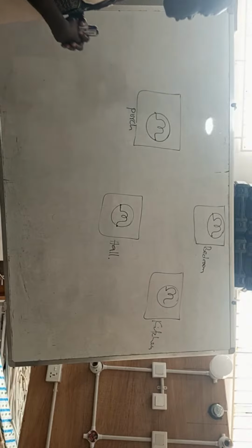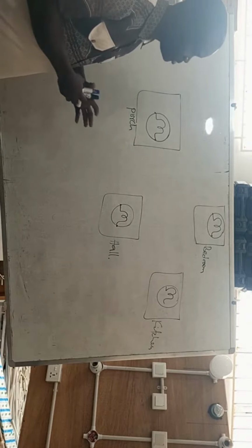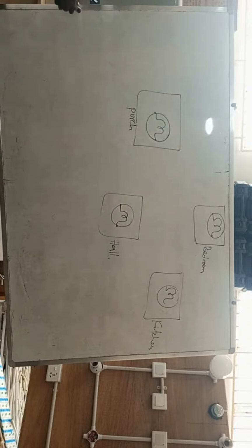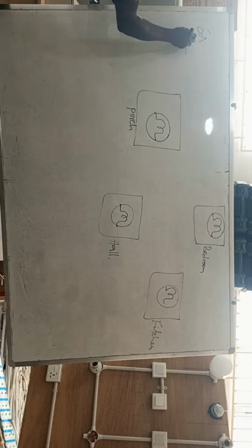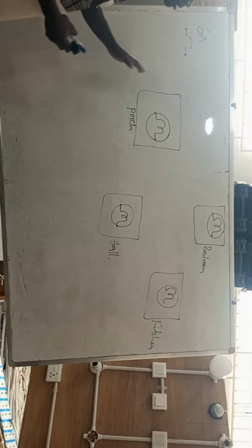All right. So in the consumer unit, for a lighting system like this, if you are using LED lamps, we can select a 6-amp breaker to protect this circuit.